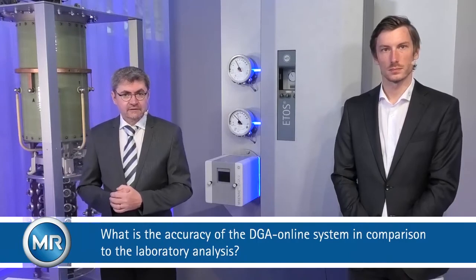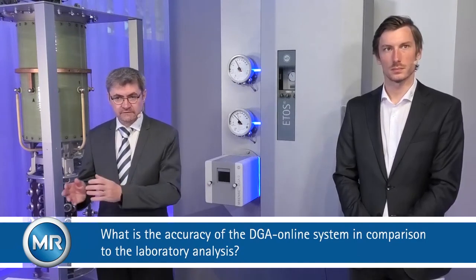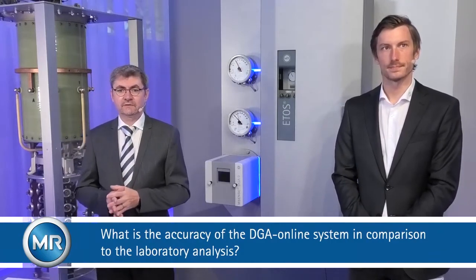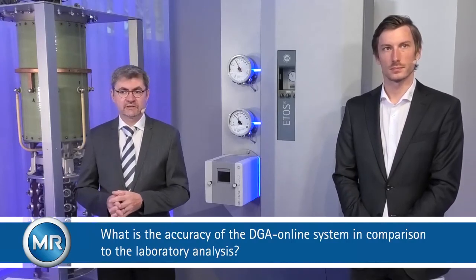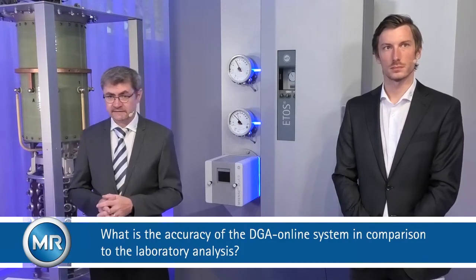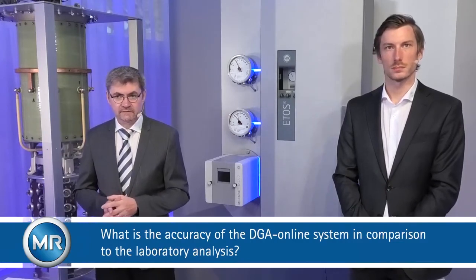When you look at the repeatability, so at the results of one system, with several results over 1 hour, for example, then the repeatability of online systems is quite good, because you have automated sample taking processes integrated in these systems. Or like the DGA 2 and 3, the system is mounted directly into the transformer tank, so there is no sample taking in that sense. And there you have measurement uncertainties of 5 to 8%.